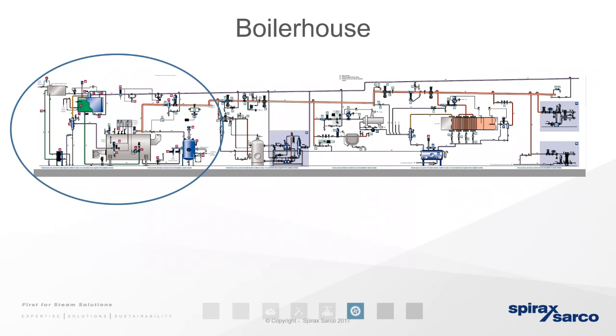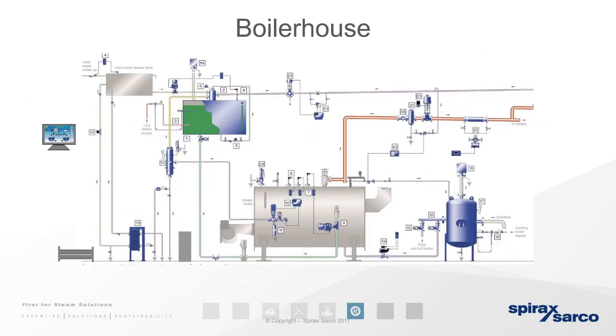Having a look at the boiler house, our energy center where steam is generated. Now, some consultants will never get involved with how steam is generated, but it is important to have a good understanding, as a failure to do so can have an impact on ongoing safety, maintenance, and absolutely process issues. The main components in this boiler house are definitely the boiler itself, the hot well or feed tank, and the blowdown vessel.